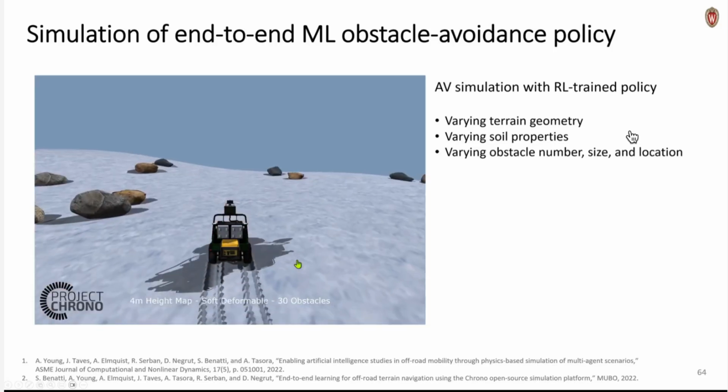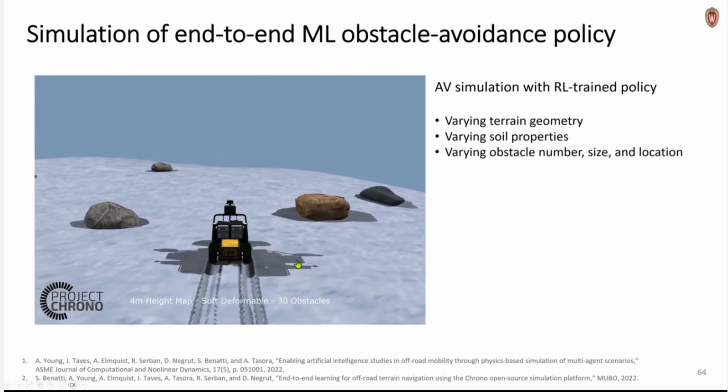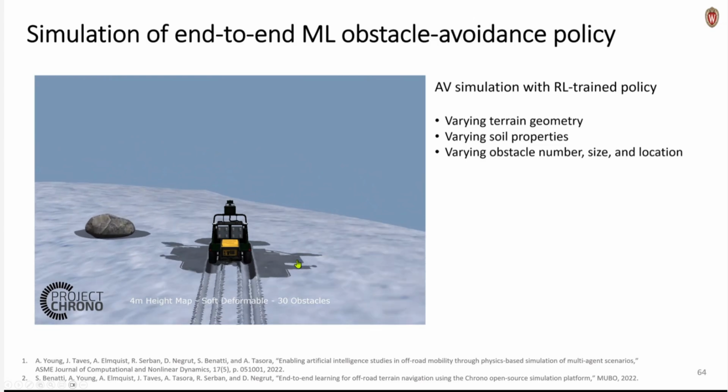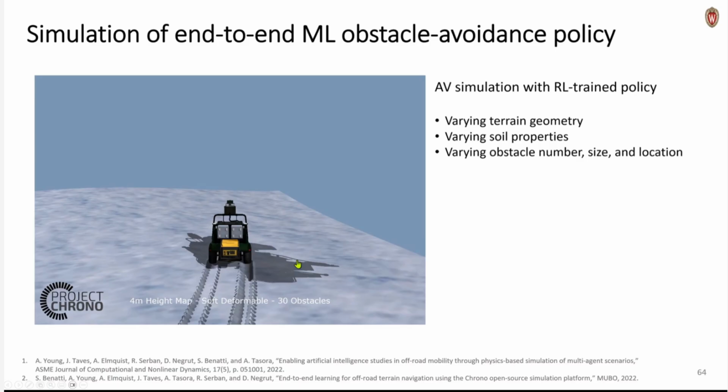And this is a so-called end-to-end approach to autonomy, meaning that the input was just what the camera and the LiDAR, the sensors, see, and the output was directly commands to the vehicle. So we didn't do any perception or planning and control. We just take the inputs from the sensors and train this neural network that produces controls for the vehicle. What should be the steering input? What should be the throttle and the brake of this Gator vehicle here, John Deere Gator?